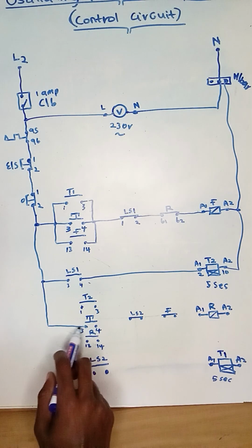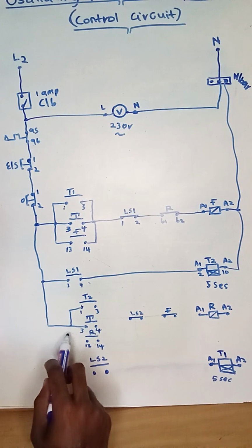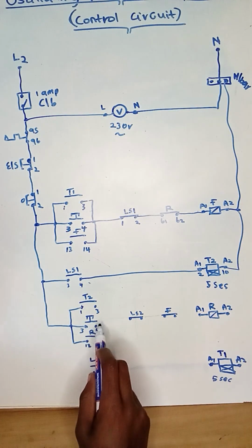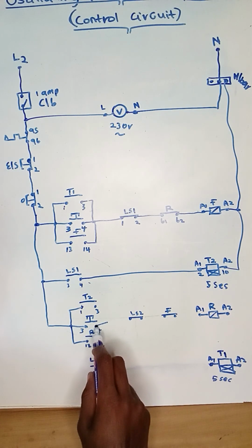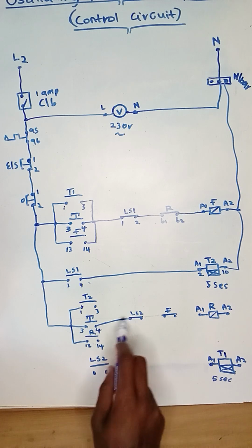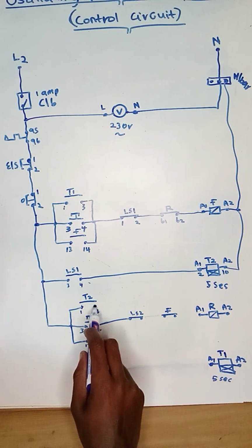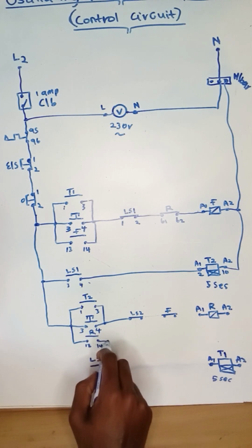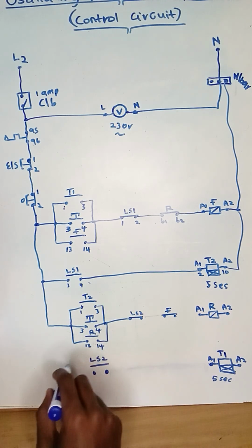And this current, again, will bridge to the open contact of timer 2 and also be bridged to the retainer of reverse. And again, out of the start button for reverse, which is number 4, it goes to the in point of limit switch 2, normally closed. Again, from normally open timer 2, it will be bridged here, and the retainer of reverse will be bridged here.